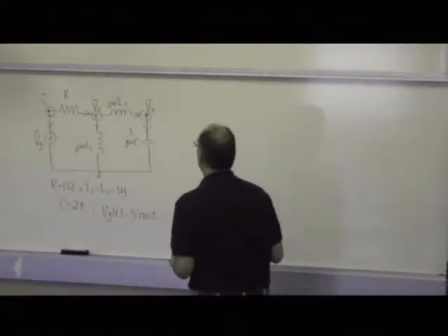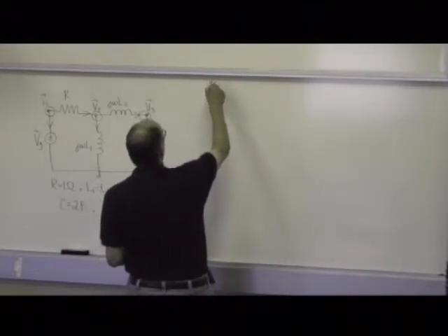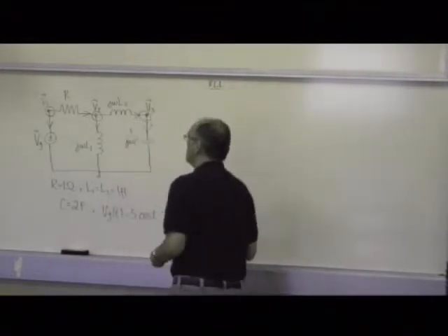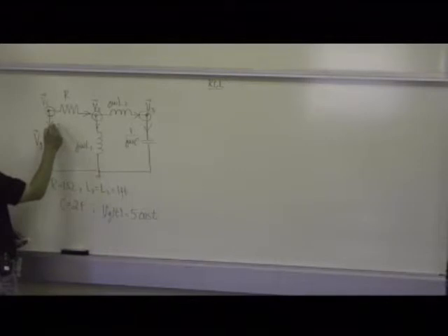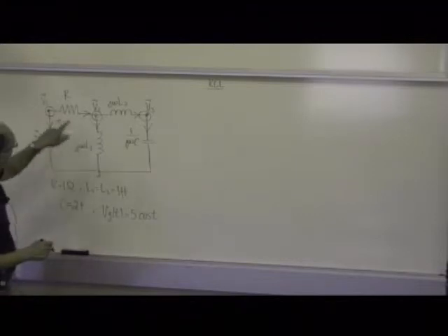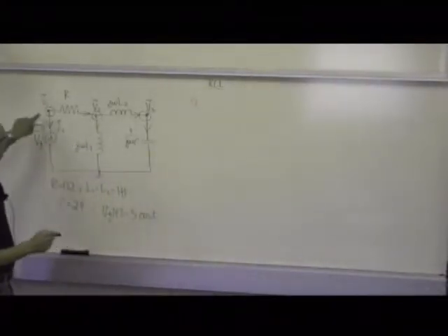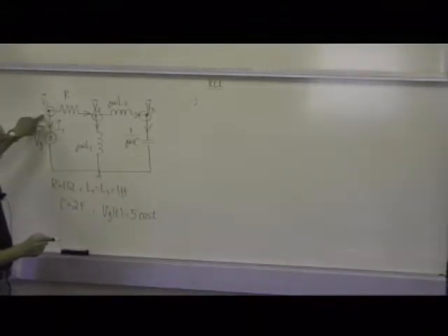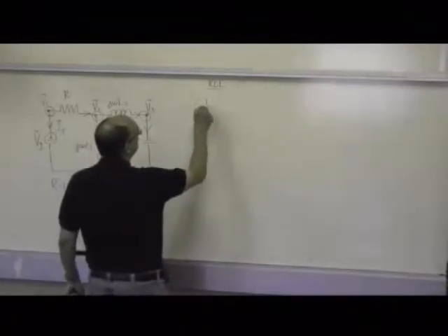And that shouldn't be too hard. That'll give me 3 equations to work with. I will label this current that flows through the voltage source with I1 again. And with that, I can now start writing the equations. My first one, for this node to the left, for node 1, is going to be I1 plus IR equal to 0.